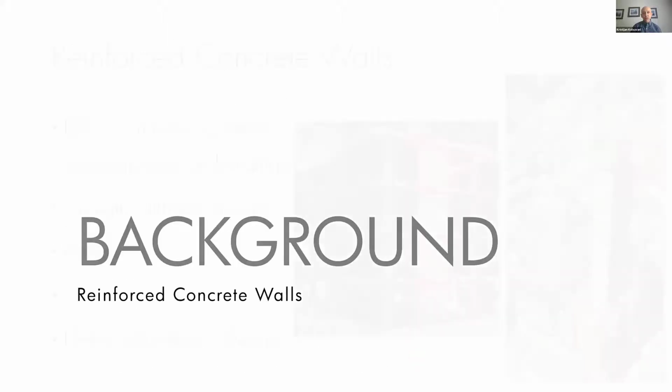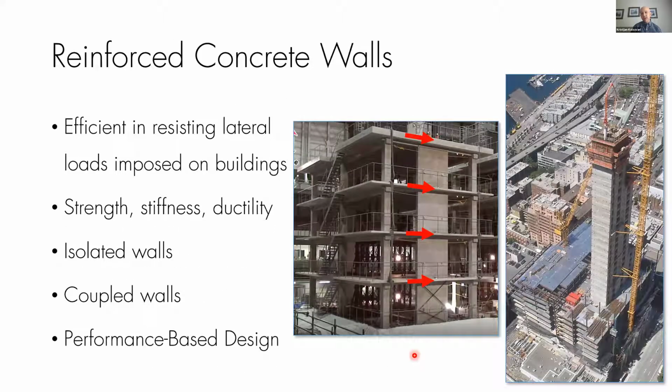So just a little bit of background. Reinforced concrete walls are very commonly used worldwide to resist seismic forces, because they provide large strength and stiffness to the structural system. You can find them as isolated walls, such as this wall over here, or as coupled or core walls, such as this picture over here. And given that performance-based design is more and more used in the design and evaluation of buildings, using nonlinear models is very common, and having good models to perform these tasks is really important.